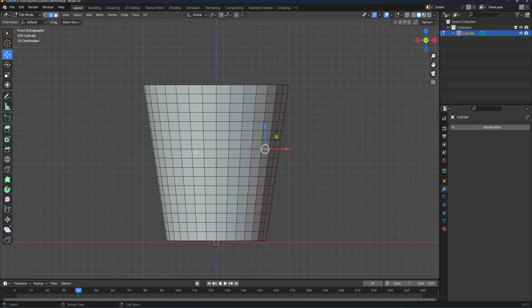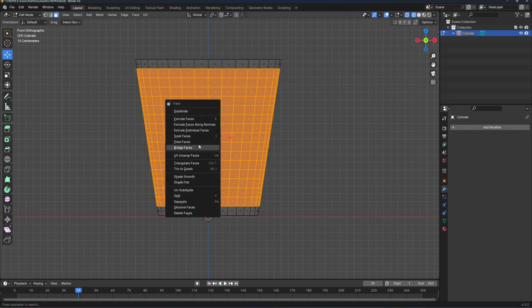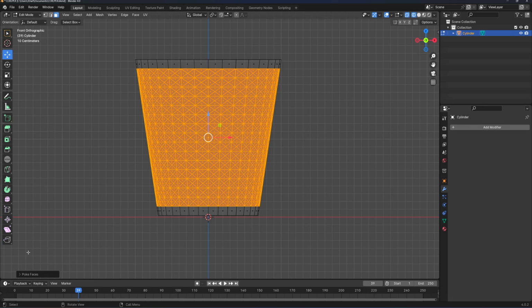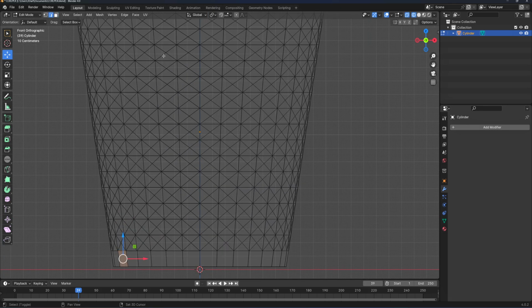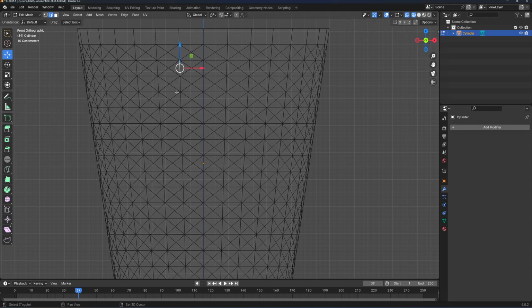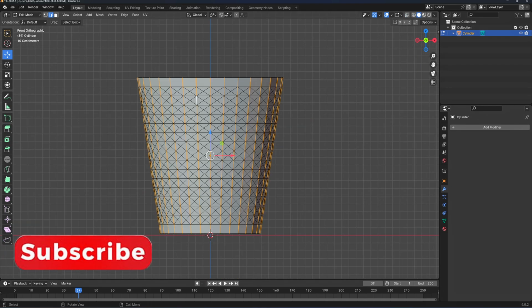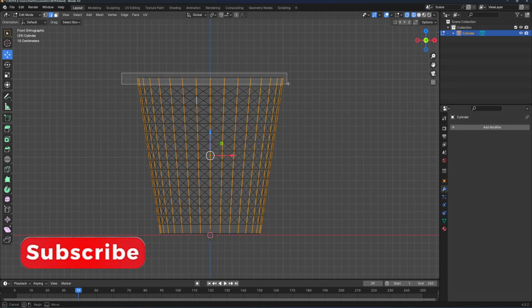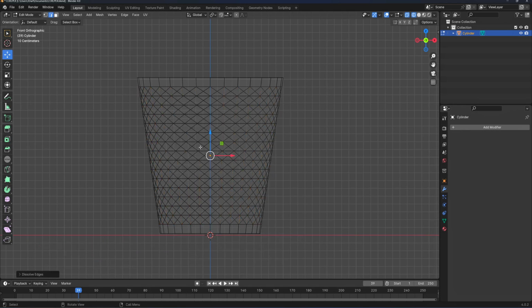And now going to front view, I'll go to wireframe mode, I'll select the faces. Selecting these here, I'm gonna need to right click and bevel the faces. Proceed. And now let's go ahead to edge mode. I'll select that edge here, doesn't matter, you can select that as well. And Shift and G, select based on the length. And now we need to deselect that loop here, so I'll go ahead and deselect the bottom and the top before doing that. X and dissolve the edges.